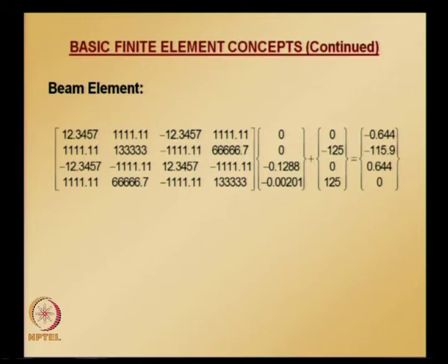What are the equivalent nodal values of moments and shear that we need to apply? That can be calculated using the element equations for the beam element multiplied with V1, theta 1, V2, theta 2, and applying the fixed end correction we get the corresponding shear and moments.